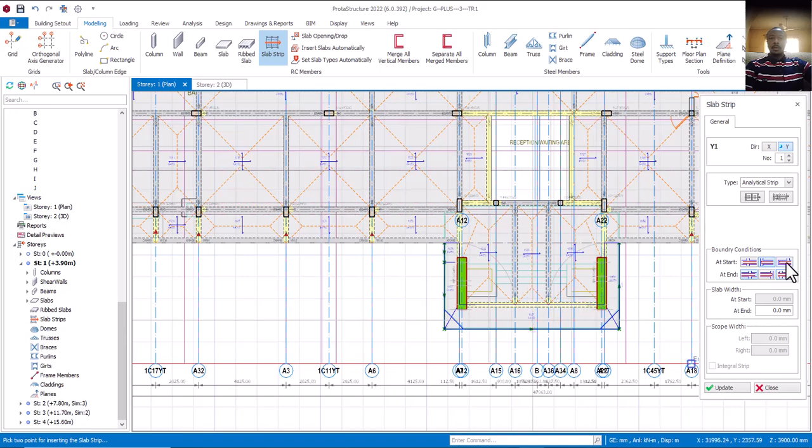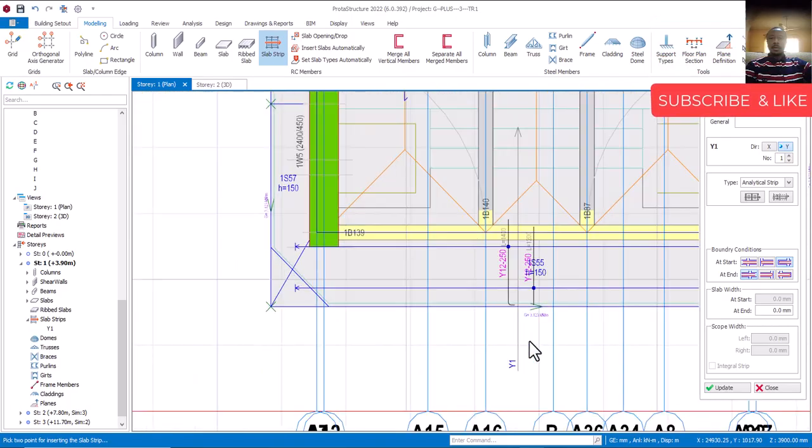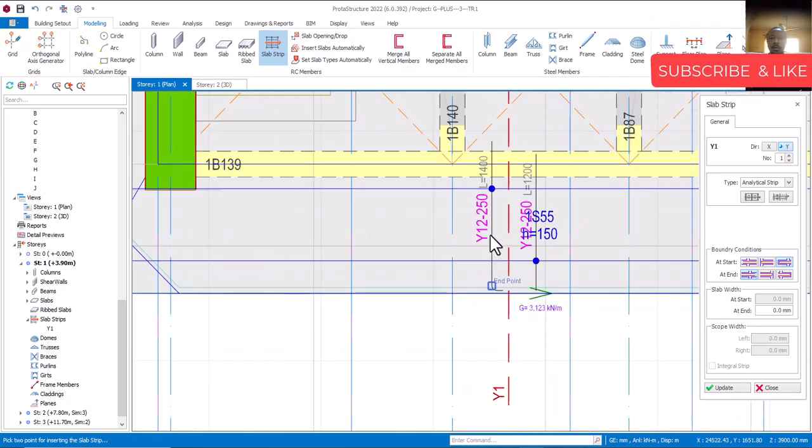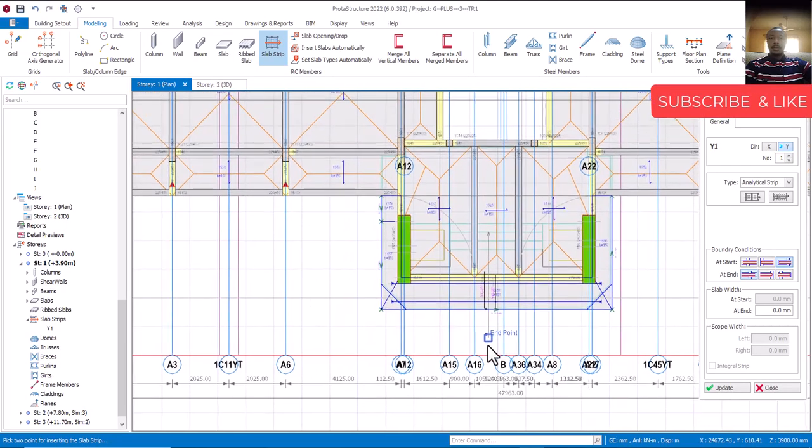I'll now change the orientation from cantilever to slab. That means from this place now, to slab. I'll come here, click on this, and let's wait for it. Correct. So can you now see our reinforcement? 12Y at 250 spacing. It has passed. Is that okay?